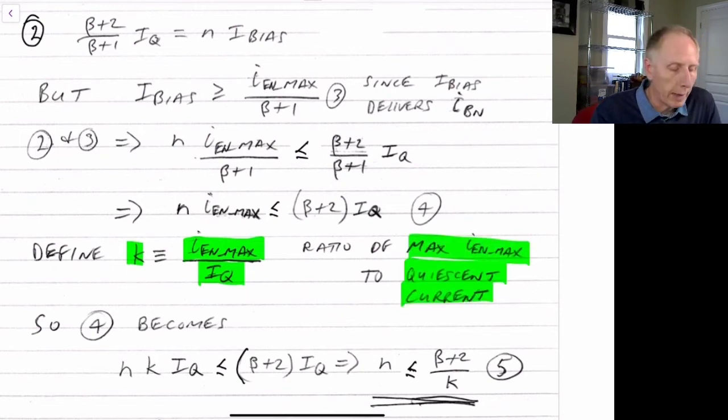And this is normally a number you'd like to know. You typically don't want that to be extremely high, but if you make it too low, you're wasting power. Your quiescent current then is high, you'll get better linearity, but you'll burn more power. If you make it extremely low, you run the danger that first off, you'll get worse linearity because your output impedance and things will be changing more significantly. But you also have the problem that it may be more difficult to bias it, that any thermal gradient or other things that come into play could affect the bias currents.